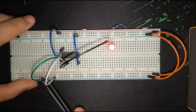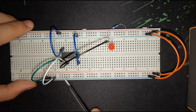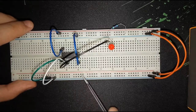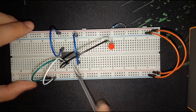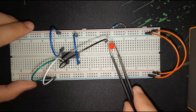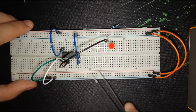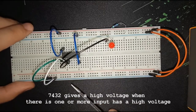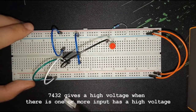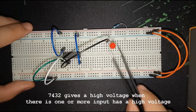So under your OR, let us go back, if there is a statement that is true, naturally it lights up. So if all false, it will be off, or your output is false. So 7432, or the OR gate, gives a high voltage when one or more inputs have a high voltage. So that is what I said earlier.